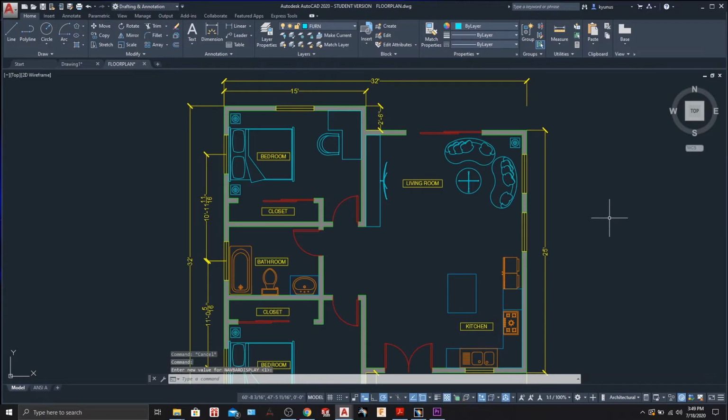If I close it for now, and let's say you want it back, you can type NAVBAR and press enter. Now you get the option for on and off. It's already off, so we want it, so let's go for on. So we have our nav bar back on the screen. Now you can also use the same command to close it, so you just have to use the off option.